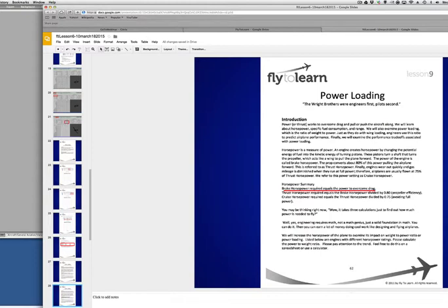But as you can imagine, as in your car, not all the power you're developing makes it to the tires. Same thing on an airplane. Not all that horsepower is immediately converted to energy that can pull the plane past drag, overcome drag and inertia. That has a lot to do with, for example, propeller efficiency. So what we say is we divide the value we think we need to overcome drag by 0.8, 80% in other words.